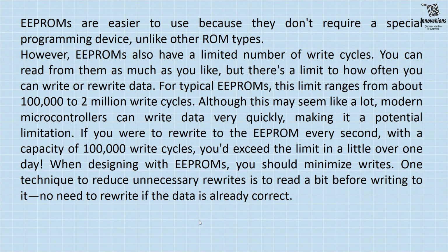If you were to rewrite to the EEPROM every second with a capacity of 100,000 write cycles, you would exceed the limit in a little over 1 day. When designing with EEPROMs, you should minimize writes. One technique to reduce unnecessary rewrites is to read a bit before writing to it. No need to rewrite if the data is already correct.